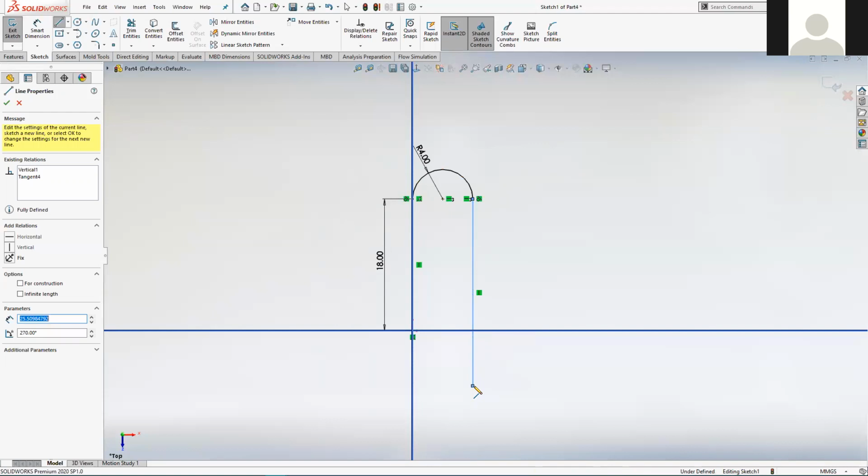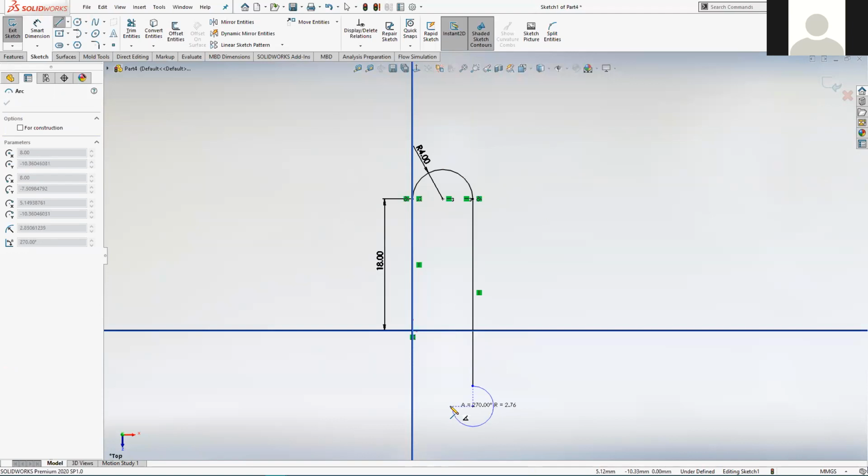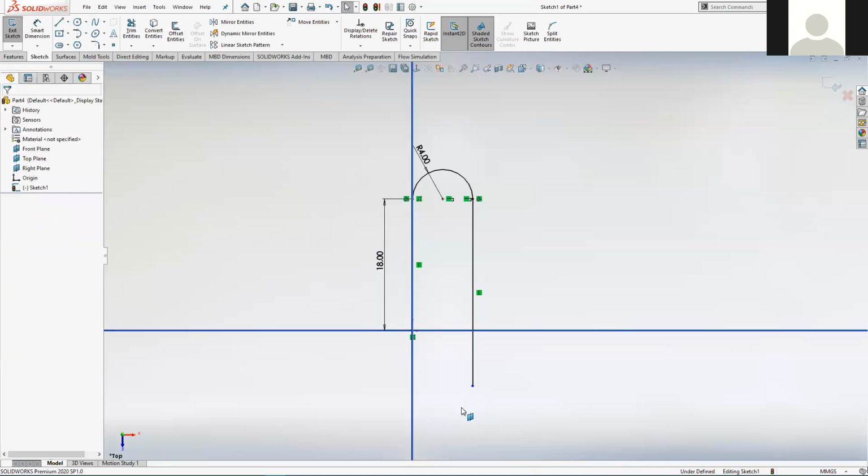It's a difficult one to get the system to do, but if you move away from the end of that line and then go back towards the endpoint and then come away again, it gives you the arc tool, although it's not giving us the correct arc tool there. So we probably press escape. That's a little trick that's supposed to speed up your sketching. You can switch on the fly from a line tool to an arc tool. But in our case, it's not that useful because it's not giving us the tangency. It's gone off at right angles. So I'm going to hit escape.